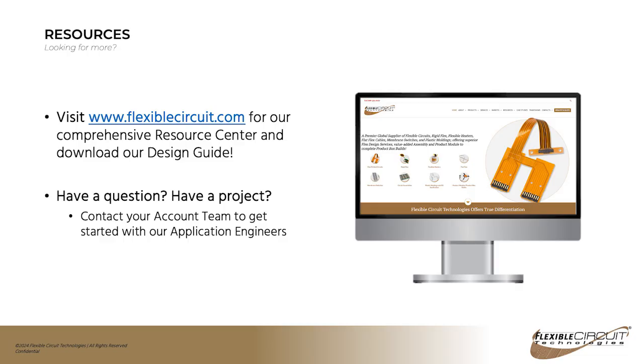You just have the one connector. One thing that I would caution you on, there's two different types of ZIF connectors out there. There's a single row, which has been in use for about 30 years and is very reliable and tried and true. There's also a dual row ZIF option, and those have been problematic for the industry in general.